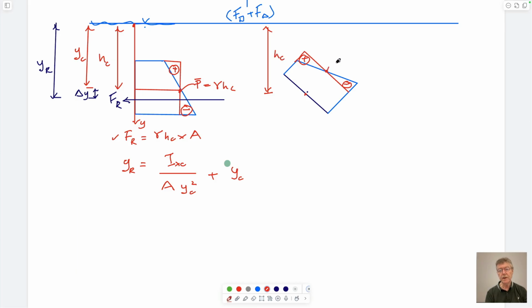So this is the average pressure, P bar. And of course this term here is the average pressure: the depth of the centroid and unit weight, the product of the two. But now, importantly, the y-axis, which I'll draw in green, does this.